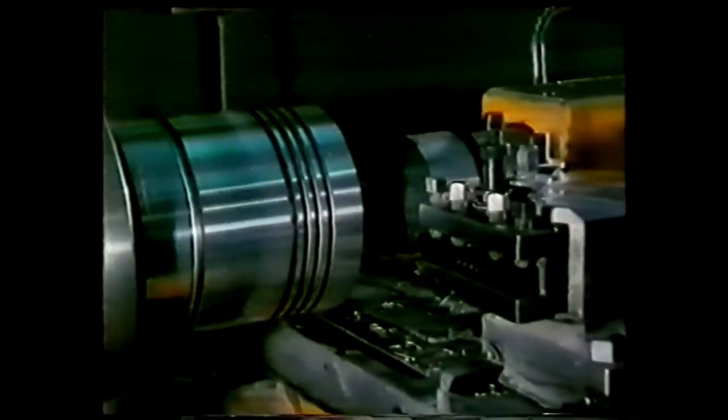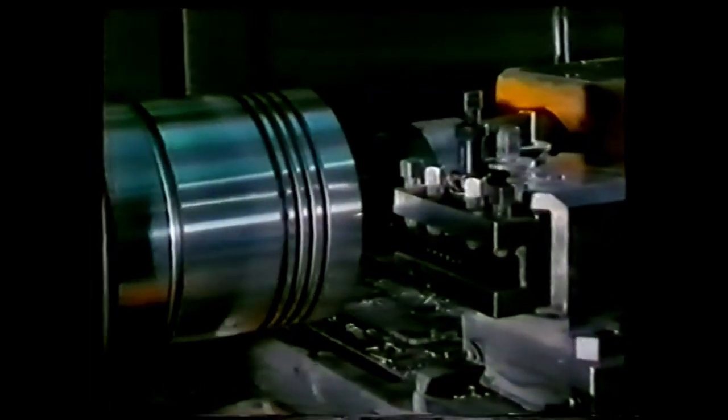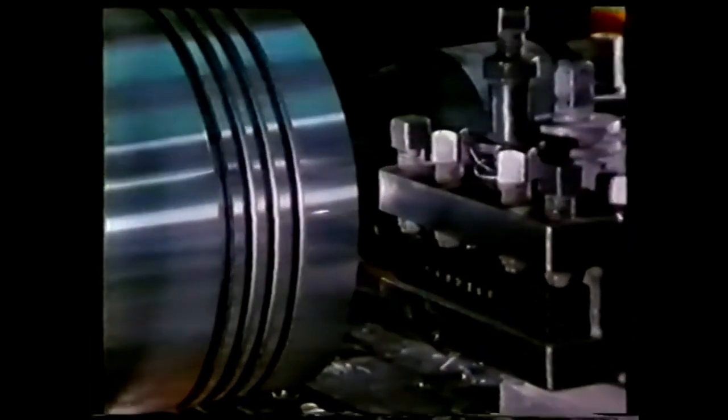These tools can be used for a variety of cutting processes with non-ferrous metal, and they're particularly efficient for cutting aluminium alloys and castings such as pistons. These alloys, which contain highly abrasive silicon particles, a test for any material, are easily machined. A synthetic diamond tool, although initially expensive, can last up to 10 times as long as the tungsten carbide equivalent, even when used for intermittent cutting.